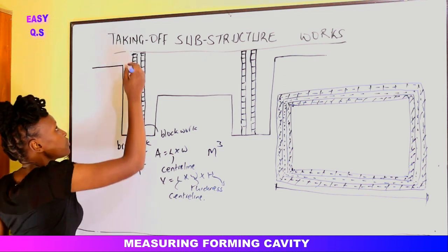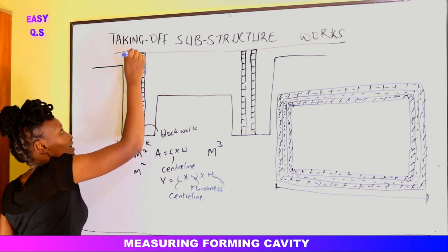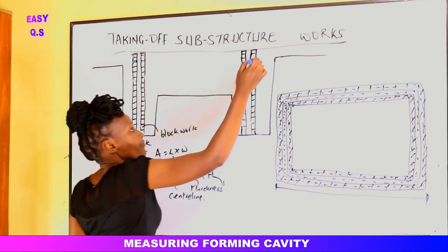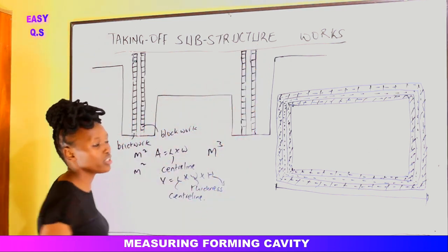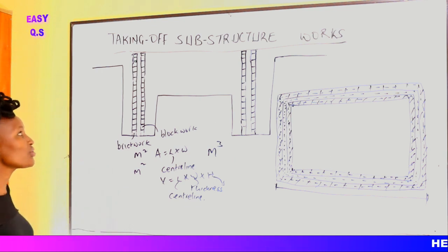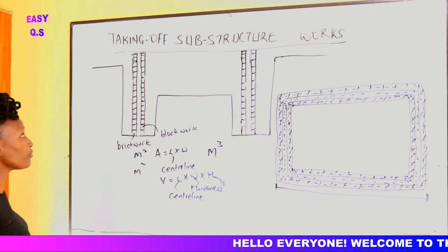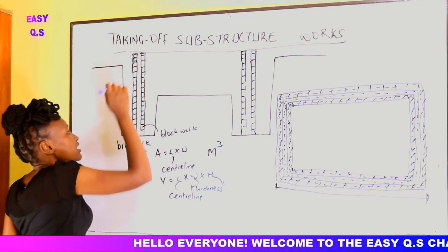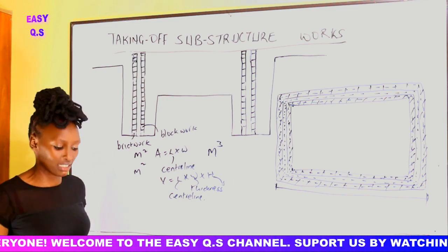But these bricks which are here, you see this, if this is the ground level, these bricks that are here and here are on top of the ground, so they are facing bricks. We need to do some adjustment, some change to the brickwork that we had taken off. So these two courses, we need to adjust them, and they should be on the superstructure side.